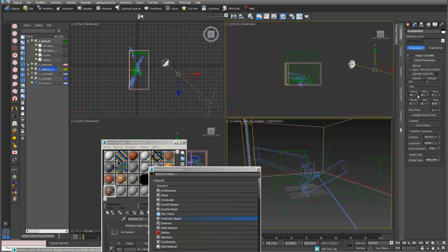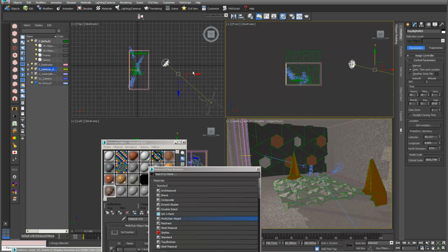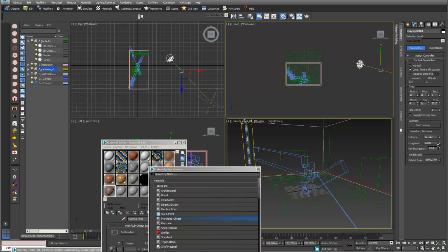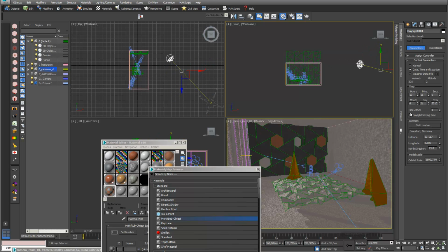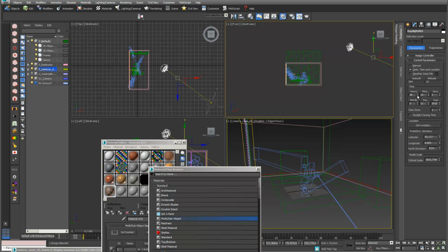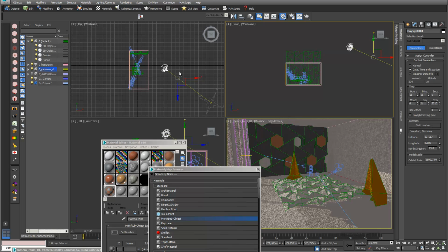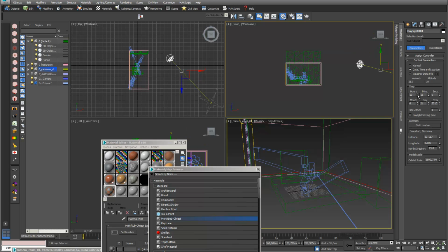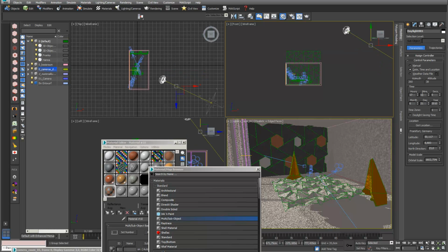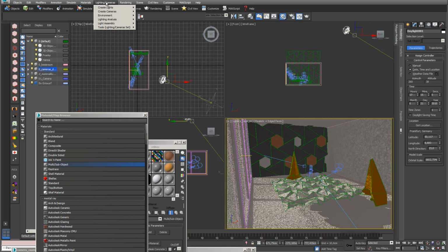And one big piece of advice: always see that direct light comes into your room, otherwise your scene will collapse because the light doesn't have anything to reflect. So you always should change that with your north direction, somehow like this. And I just go to something like 6 o'clock in the afternoon again, or let's go to 5 o'clock. Sorry, 5 o'clock. Okay.